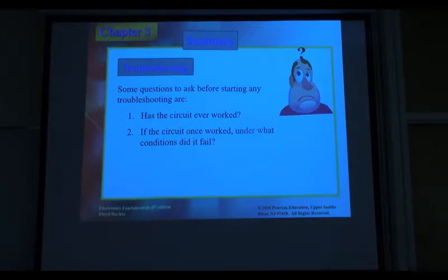So which part may be affected? Either the breaker or your circuit protector. The breaker is easy to think of. You check the breaker, that's good. Then what else? Circuit protector, that is also good. So your TV is the problem. Which part of the TV? The fuse, that's the first thing, like the breaker outside but the fuse is inside. That is why it's easy to check. The fuse is good. I don't know after that.